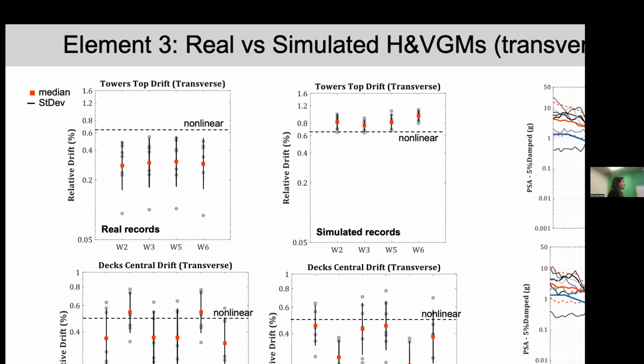So when we studied them, linking this to what we're observing in the spectrum, what we realized is that for a structure like the Bay Bridge, which is characterized by elements having completely different dynamic response, our method of scaling, the method that is proposed as part of the H2 provisions, is probably not the most appropriate one.